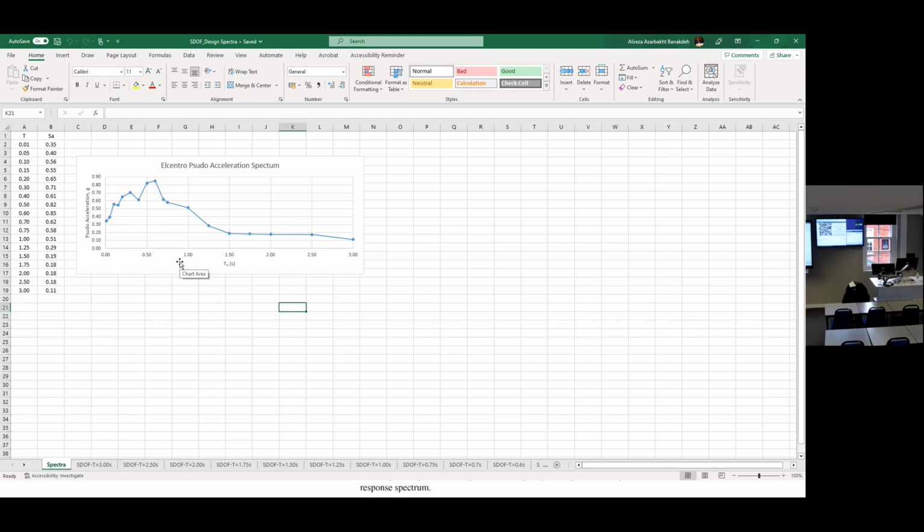But if you have the natural frequency of your structure, you say, okay, the natural period of my structure is 1.5 second. I will tell you, wait, 1.5 second. I can promise you, this is some kind of approximation for any structure. Your structure is 1.5 second. Okay, go here. You're around 0.2 spectral acceleration. Get this number, 0.2 g.